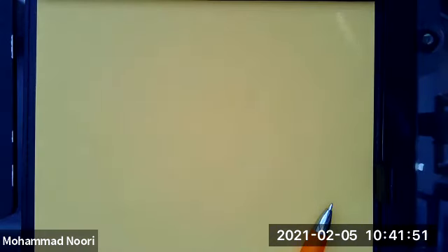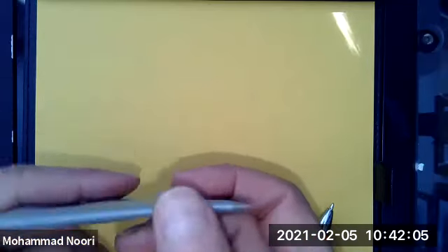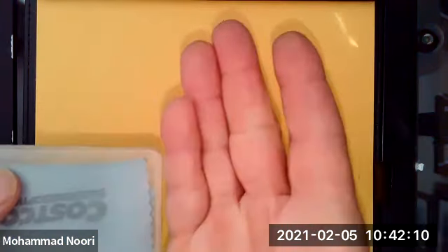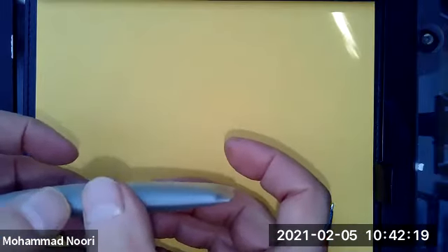Now, I have another example. This is actually a better one, okay? If you look at, this is the cross section. So I can put it like this. So the bending would be much easier than if I put the loads this way, okay, about this axis, bending takes place much easier than if you put it like this. There's no way you can bend this as simply as you did that way, okay? So that's what the meaning of the second moment of an area is all about, okay?